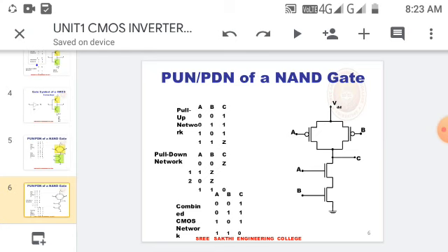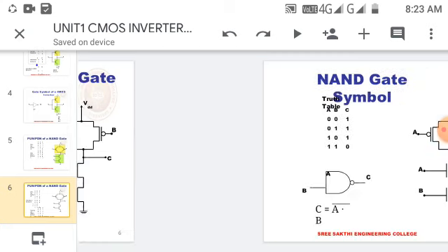If you combine for a CMOS inverter network, for 0, 0 you will get 1, for 0, 1 it is 1, and 1, 0 it is 1. Similarly 1, 1 gives 0. So this is the combination of a NAND gate. In logic, NOT plus AND gives the output 1, 1, 1, 0. Similarly we can obtain this by using this circuit of a NAND gate in VLSI circuit.